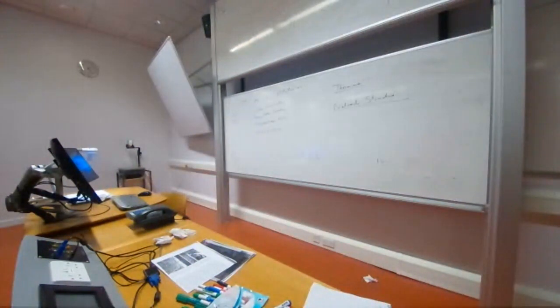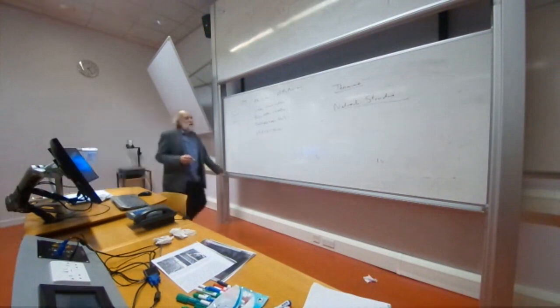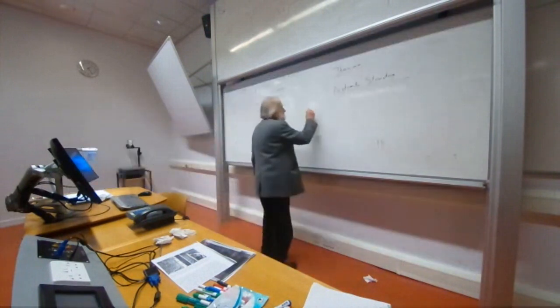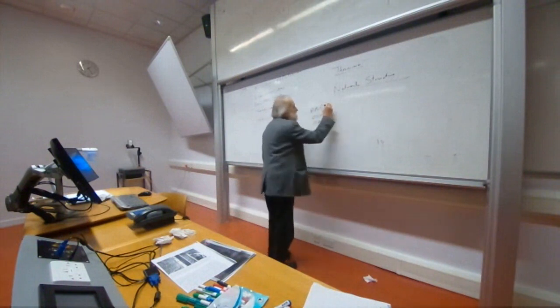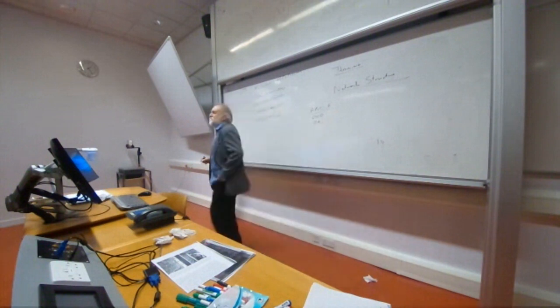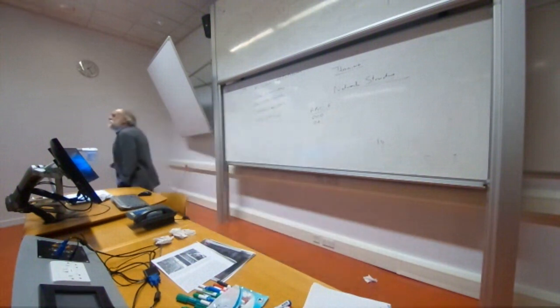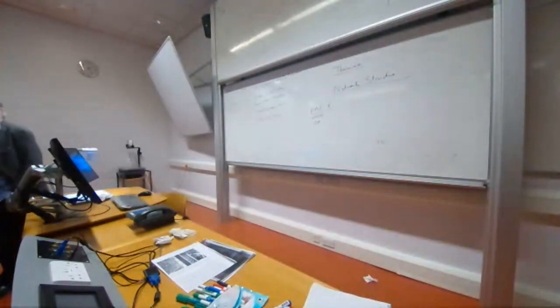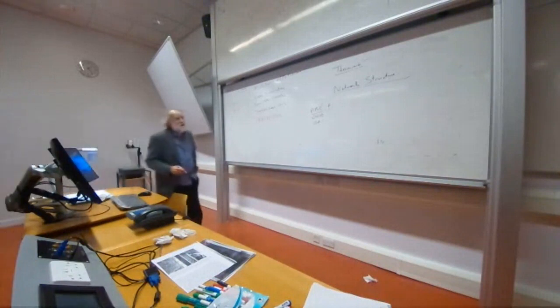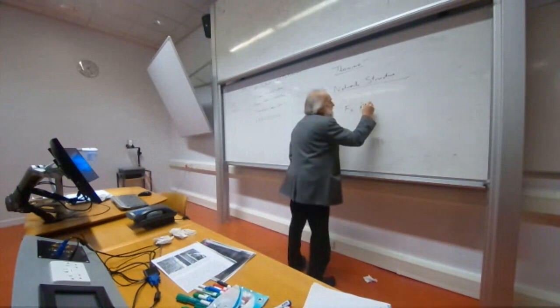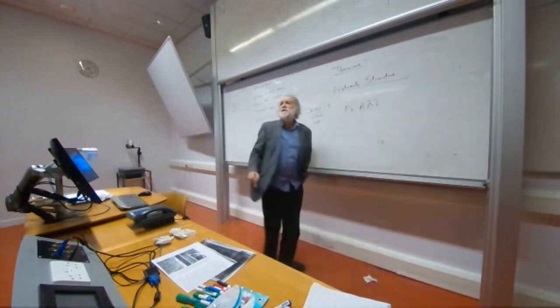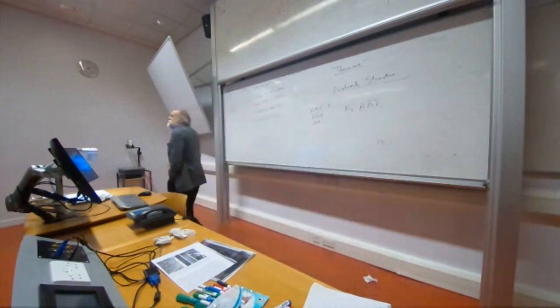And just to give you an inclination of how this works, if I'm dealing with binary data, just take two examples of a 3-input function. If I want to recognize 0, 0, 0 on A, B, C, F equals not A and not B and not C. F goes 1 when A is 0 and B is 0 and C is 0.